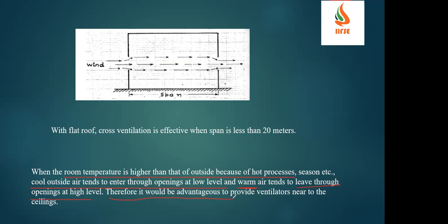Therefore, it is advantageous to provide ventilation near the ceilings. That's why we provide ventilation at the ceiling level, so that whenever the internal heat or the air gets heated up, it automatically goes out through those ventilation openings, and we get good comfort.